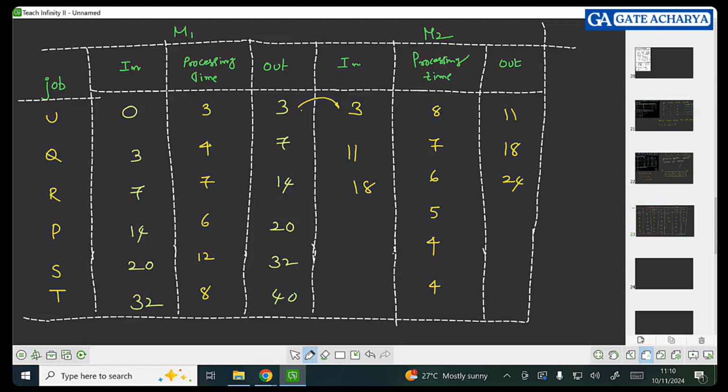Now here which one is again ready for getting machining or operation at the 28th minute, but the machine will be busy till 24. So after 24 minutes you will get it. Now here it is 29. Again, which one is higher? 32. That means here the job is finished. P job is finished by the 29th minute.